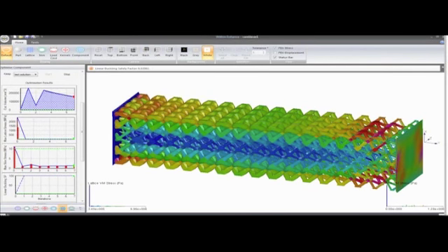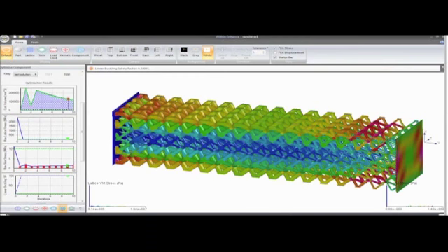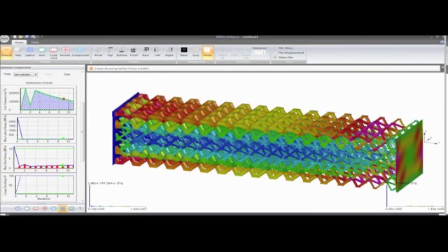So it needs to be thickened up slightly. In other areas, there's not much going on. Just like in the bone, some areas aren't really doing much. So there you can pull material out and ensure the part's as light as possible. As you can slowly see evolving here, the graph on the top left is going down. That's the weight of the component.